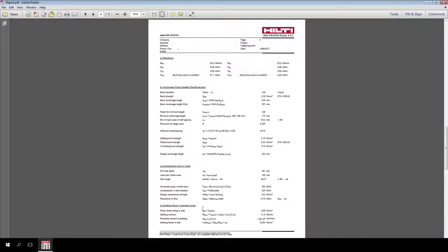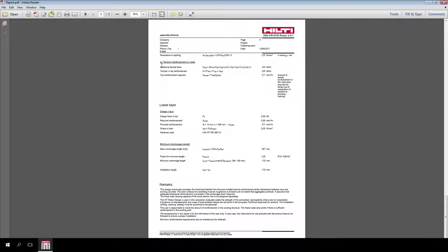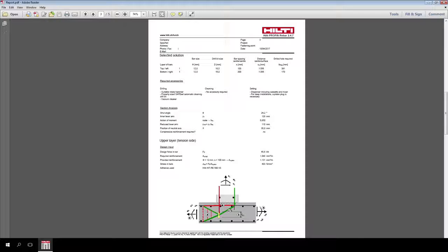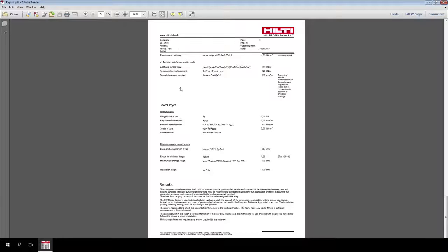the concrete. Paragraph E calculates the additional reinforcement needed in the existing slab to take up the tensile action. The user has to verify if the reinforcement located in the node area required for forces, in addition to the previous loading, is able to carry this additional tension force. Here, the calculation on the tensile side of the node ends.